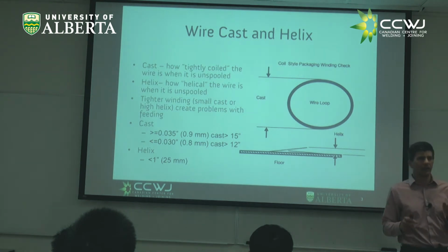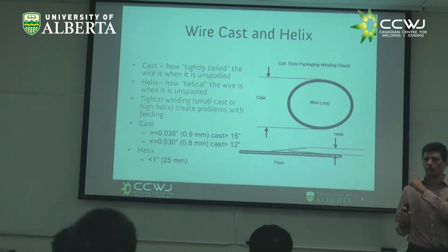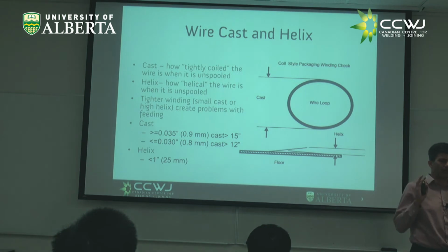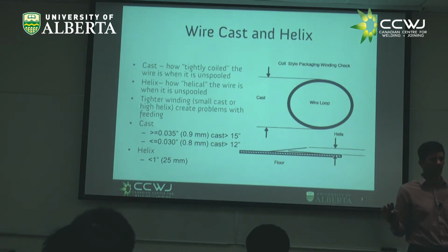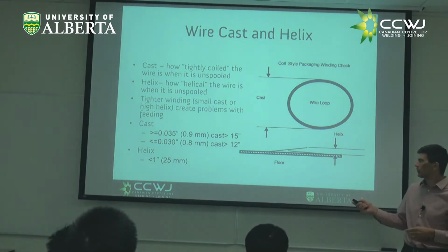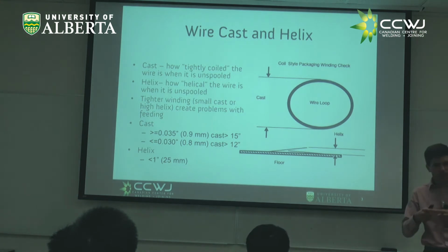Things to think about. Many welding problems come back to this. You might be having a brand name wire, and then you decide to buy a super cheap wire. Everything looks the same according to the standards, but then all of a sudden you might have problems that you're missing your joint, and you can come back to this. Or wearing out the contact tip, whatever it is. You're going to see we have sliding electrical contacts, and those can wear out depending on how bent the wire is.